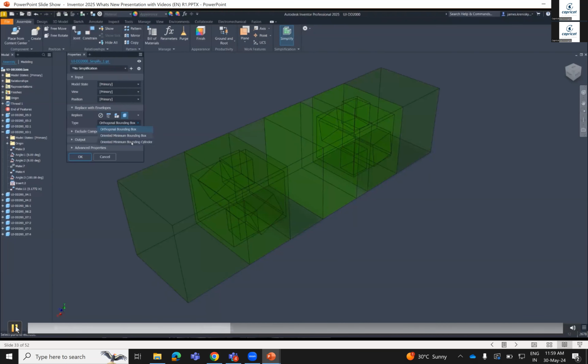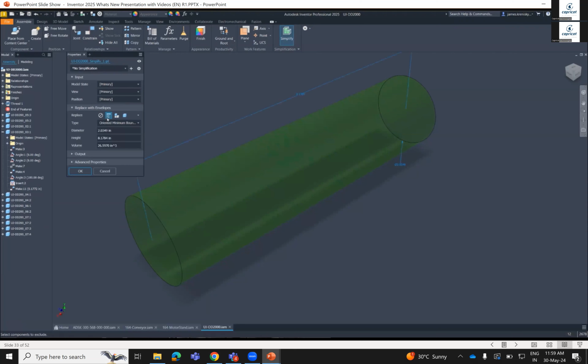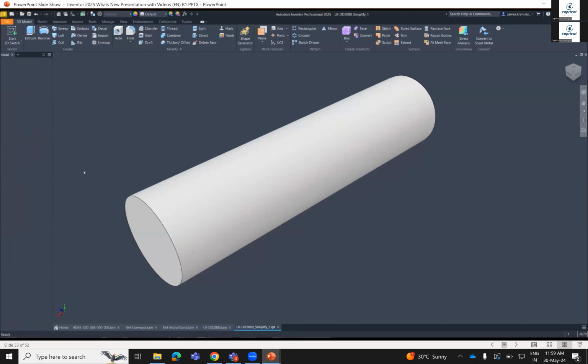Size model simplification by fitting a cylindrical envelope around components. Or if I need that part to be bounded in a cylindrical shape, you can select the cylindrical option in the drop-down menu. It offers an alternative to the traditional rectangular prism. This enhancement is particularly beneficial for models requiring tighter tolerances, as it closely aligns with the original model's shape and size.